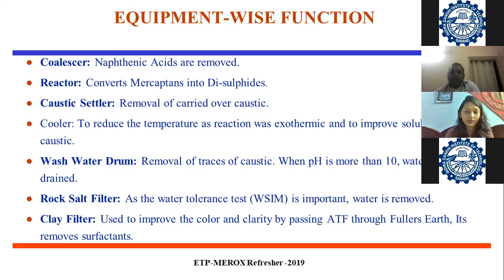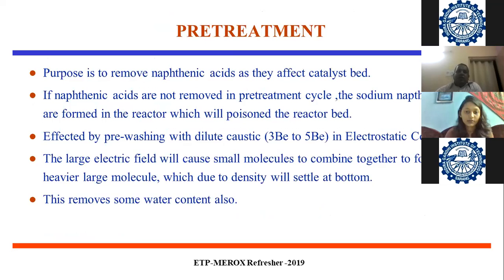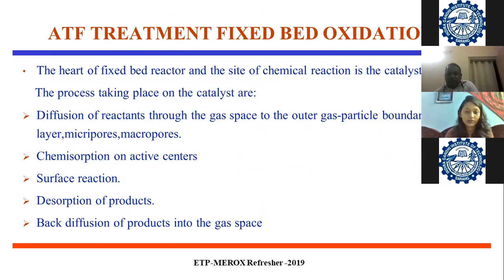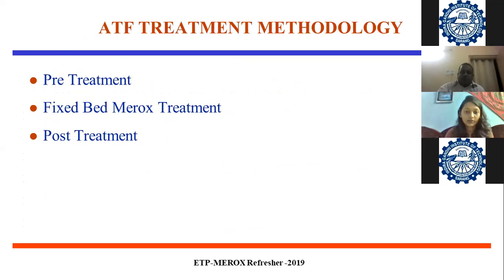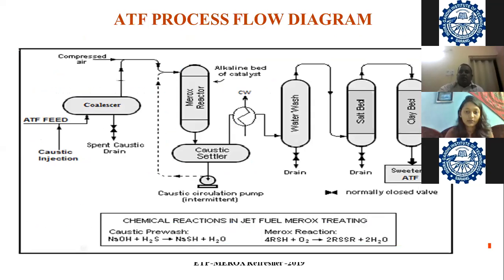So this is regarding the rock salt. Then finally, we are talking about this clay filter. Clay filter is nothing but the last filter after the rock salt filter. In the clay filter section, we improve the color and clarity by passing ATF through Fuller's earth, removing the surfactants.